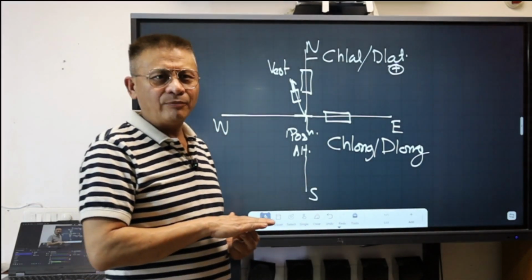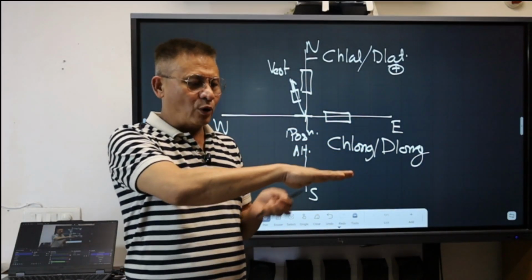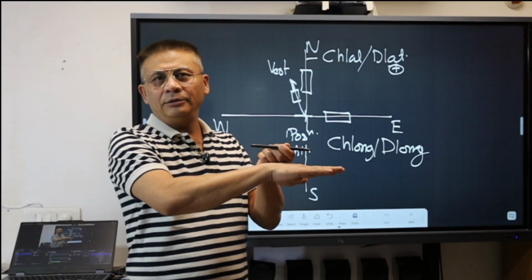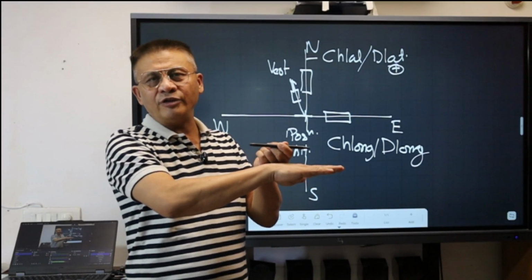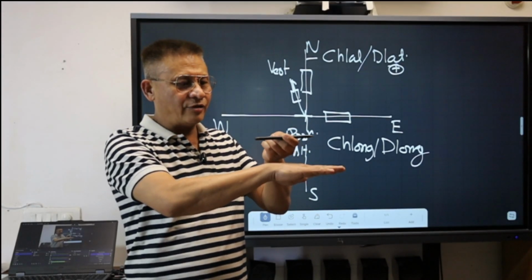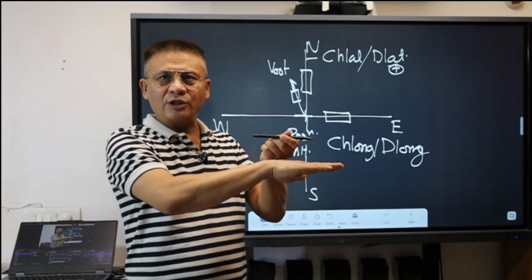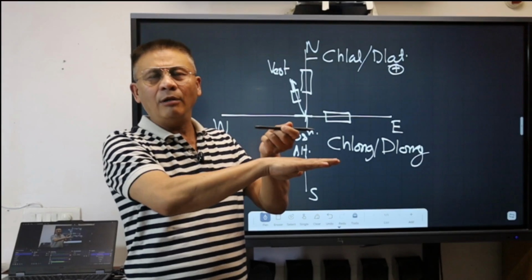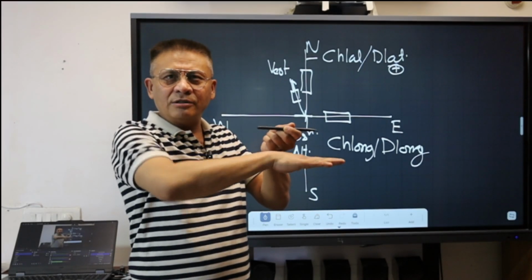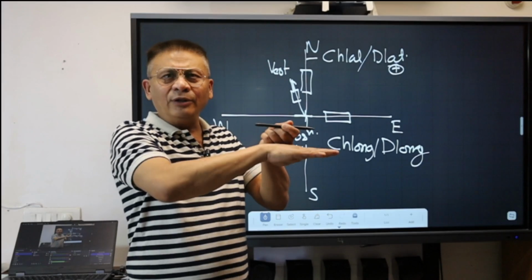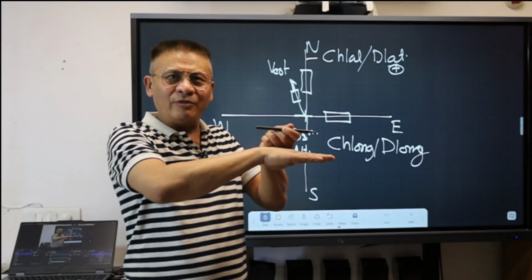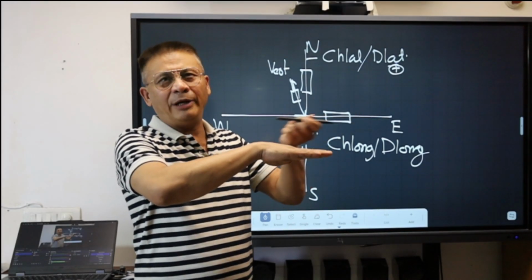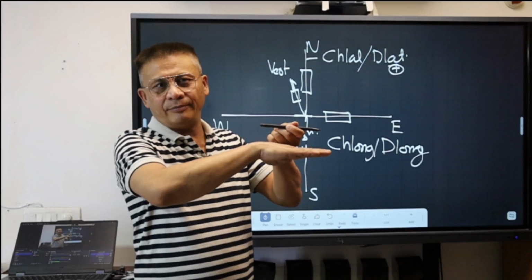We know that a gyro, because of the first law of gyrodynamics, will try to maintain the direction in which it is aligned. Now let's see that. Let's assume that the pen in my hand is the gyro axis on which the accelerometer is mounted. Now the aircraft turns left, right. Even though the aircraft turns left, right, because of the rigidity of the gyro, this platform where the accelerometer is mounted will remain pointed in one particular direction.